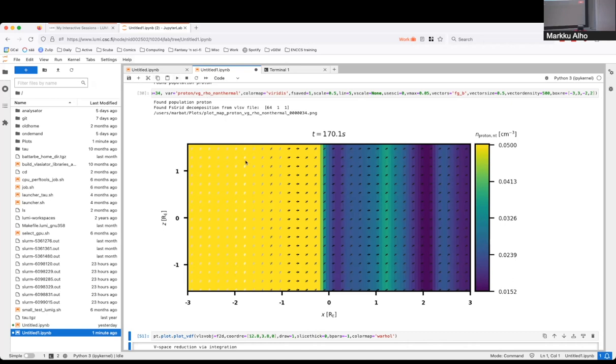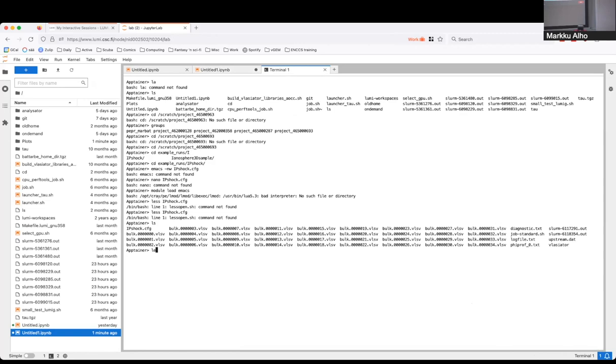I believe VisIt is automatically plotting only the in-plane components, of course, when there's a slice. So if your slice was in the XY instead of XZ, that might also be why you only saw... But yeah, so the slice operator... that's not it, because it was the X component that was getting squished away. Yeah. Okay, so it was an aspect ratio issue.